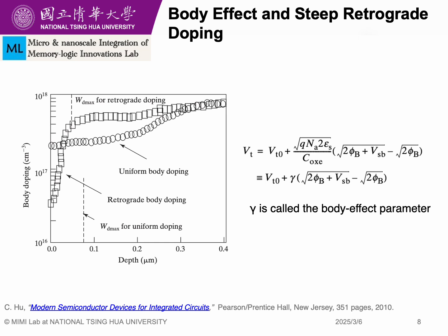Well, now what the modern MOSFET transistors employ is something called steep retrograde doping profile, which is light doping here in a thin surface, and then very heavy doping underneath. So the steep retrograde doping allows transistor scaling to smaller sizes and cost reduction, and also reduces the impurity scattering. The depletion layer thickness is basically the thickness of the lightly doped region.